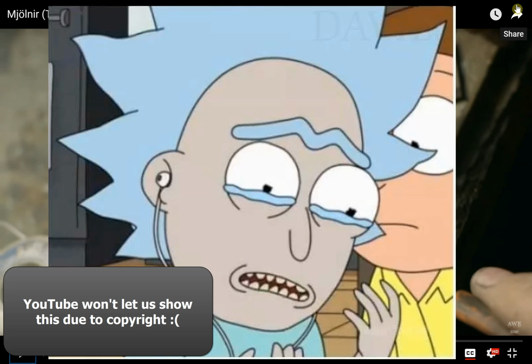They're doing something called brazing. What on earth is brazing? Anybody know what brazing is? In years past, we had lots of fabricators in this class, who answered these questions left and right. So brazing is basically soldering, but on a larger scale, right? You still use something kind of like a solder that you heat up. You take the two materials, in this case the copper and the bronze, or whatever that inlay is made out of, in the bronze. You put the solder type material around it, all over it, and then you blast this thing with